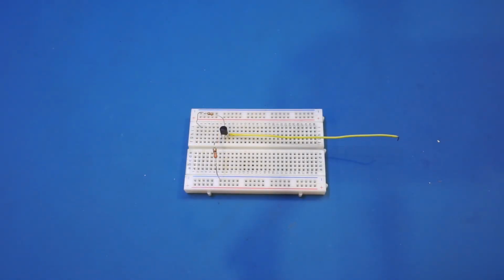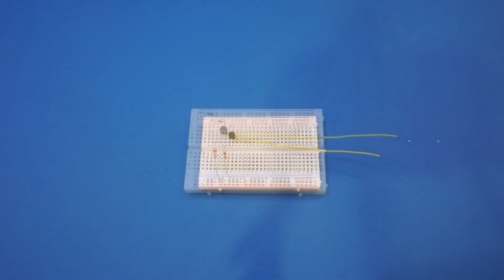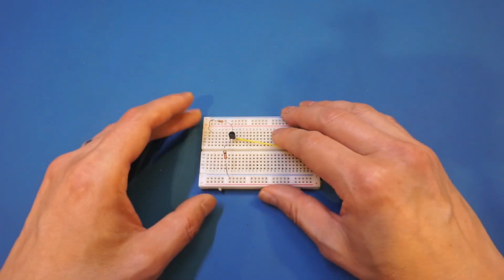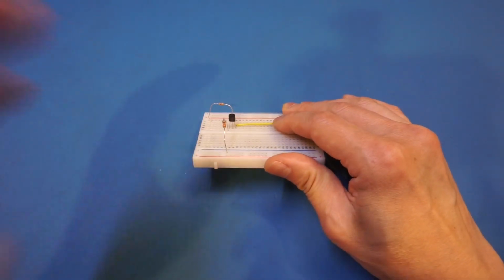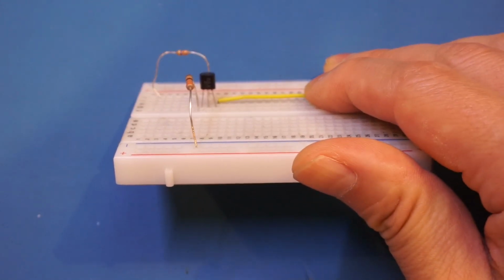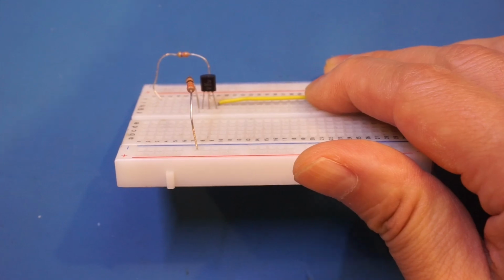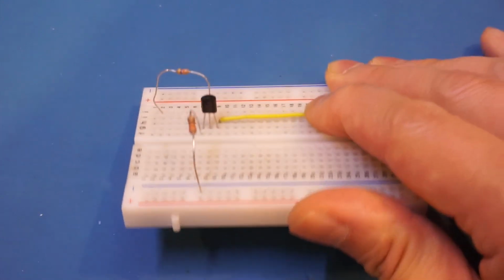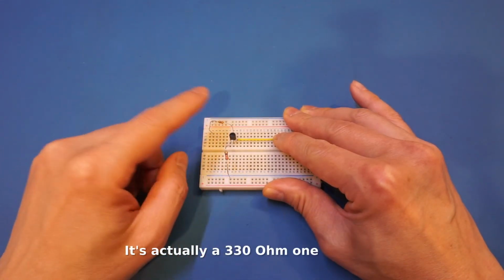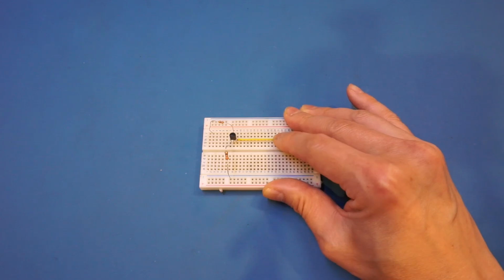Now with these limitations in mind, let me use my UTG 962E and the 2D72 to generate these required waveforms and hook up an oscilloscope and see what we got. By the way, it will get rather messy after I hook up the probes, so I thought I would just show you what I have currently on the breadboard here. So the transistor is a 2N3904 small signal transistor, that is an NPN transistor, quite common. And the resistor here at the emitter is a 1 kilo ohm, and the one on the base is a 47 kilo ohm resistor.